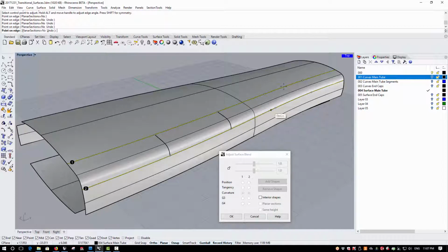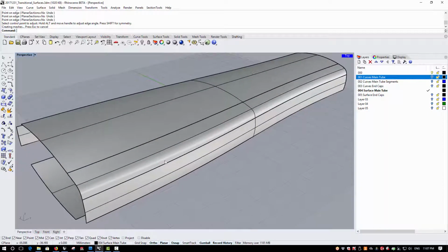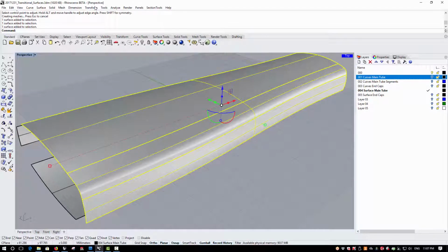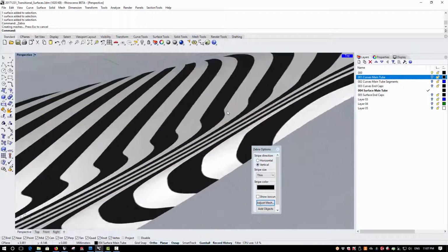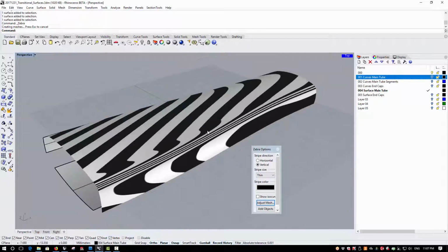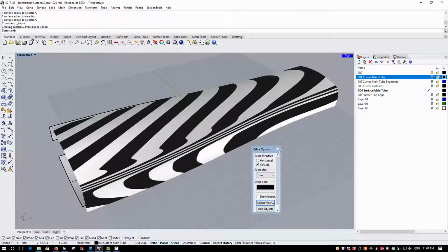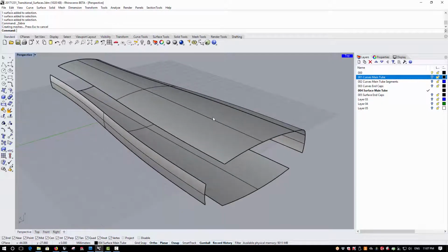And if I add my shapes between those points, then what will happen is that I won't add any complexity in terms of control points to the surface, but my match should be better. We can see now, if we zoom into that top, that this match is much tighter. So I'm going to repeat this process on the other 4 edges, and we'll speed up the video as I go through this.